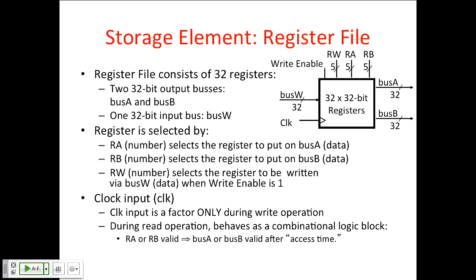So we talked about memory and just general registers. We actually need the register file that holds the MIPS state of the machine, and we need 32-bit registers to hold those values. This is kind of like a small memory, except it has actually multiple parallel paths to it, so you can actually read two values at the same time. So you have a separate address port for register A. These 5 bits tell you which register you want to have output on the output bus A, and a separate set of 5 bits give you the address of register B. Which of those 32 registers do you want to have appear on the second read port, bus B? So you can, at any point in time, have two values coming out of that memory. You can read it twice at the same time, with two different addresses. And again, these are combinational reads, so any point in time you can change the inputs, and sometime later the output will represent the new value.